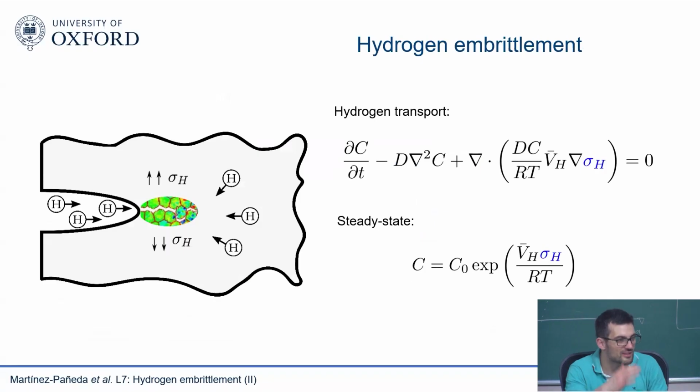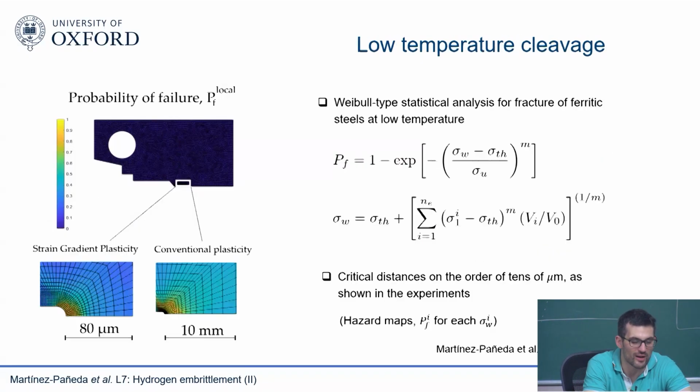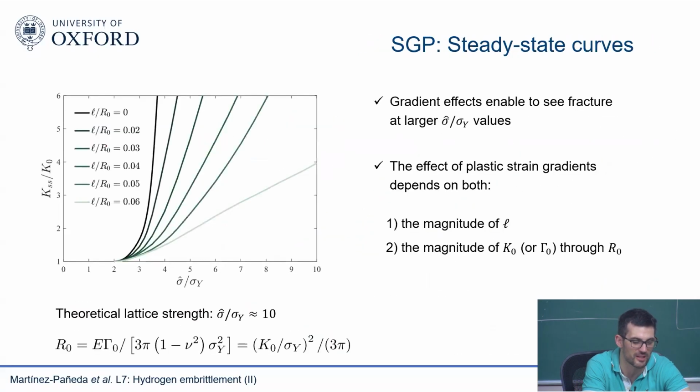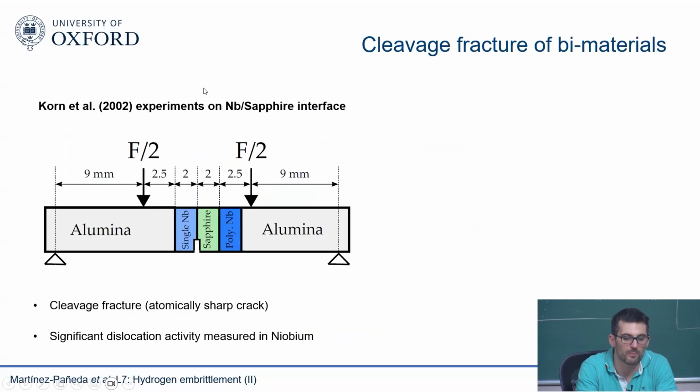Because, and we discussed this during the seminar, if you ask some of the people working with other plasticity-based mechanisms, they will tell you the problem with the cohesion mechanism is that, yes, you look at the grain boundary, you see that it has broken, but I cannot explain it, because in order to break a grain boundary you need stresses like this, and they're thinking of conventional plasticity, so the gap is simply too large. So would it be relevant as well?